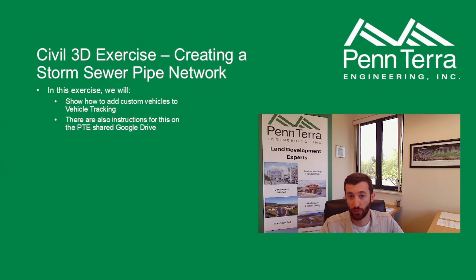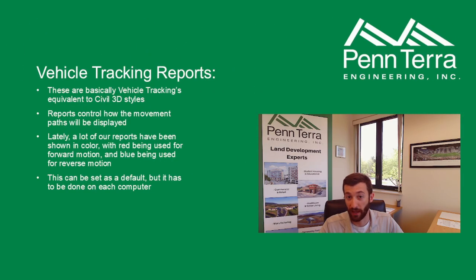So now I'm going to show you vehicle tracking reports. These are basically vehicle tracking's equivalent to Civil 3D styles. So they call them reports, but really what it is controlling what is displayed on plan view for your movement. So that would include whether you're showing the body outlines, whether you're showing just the outline of where the wheels are traveling versus if the body overhangs the front when it goes around turns, you can control how that looks.